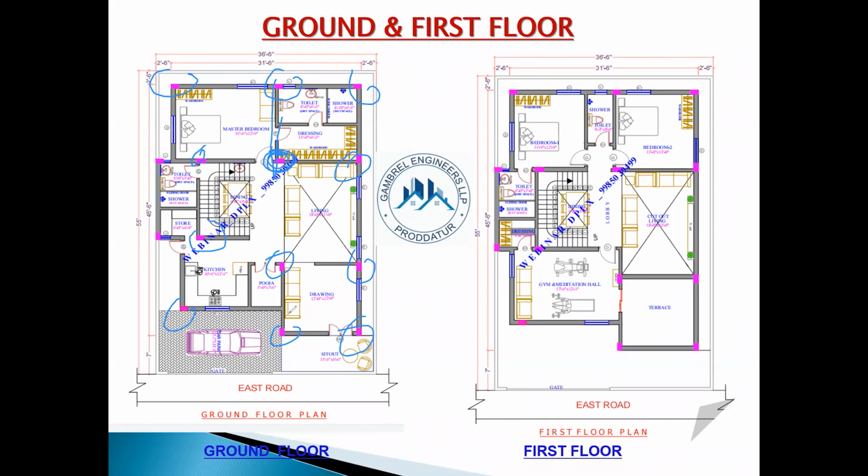Now the next question is, some people will ask, sir, why not have a column even here also? When you keep it here, the distance between these two would be very small. What is the necessity of having one more column here, because we have a very close column here also? So better we should not have a column here. Keep the column here, so that the beam resting on this point would be fantastic. So we'll have a column here, and we can have a connected beam here, and this beam is going to rest on this point, which would be absolutely fine, right? So this is another reason.